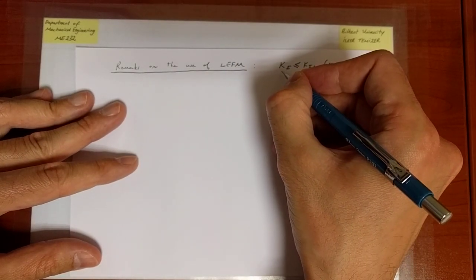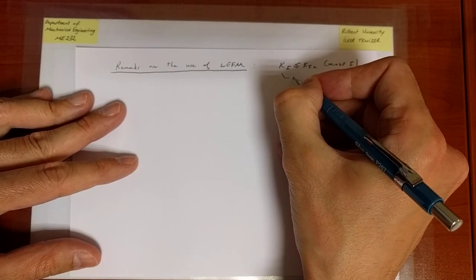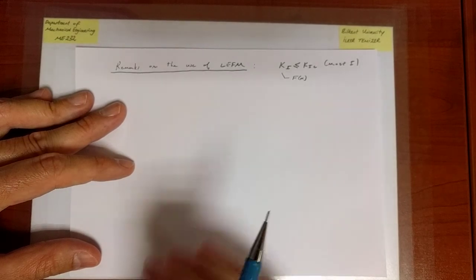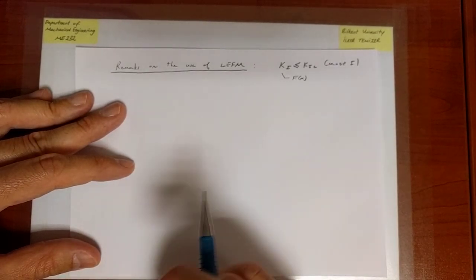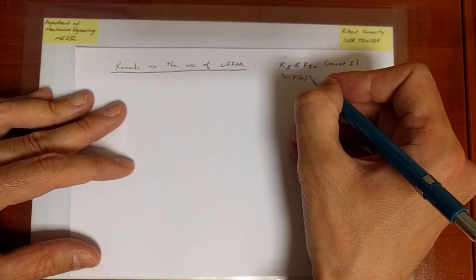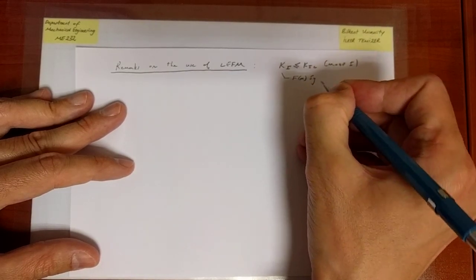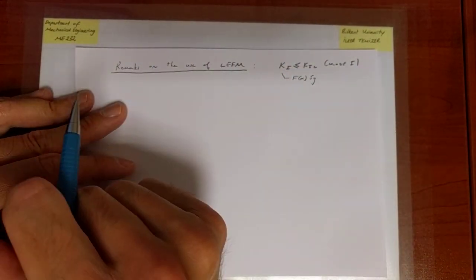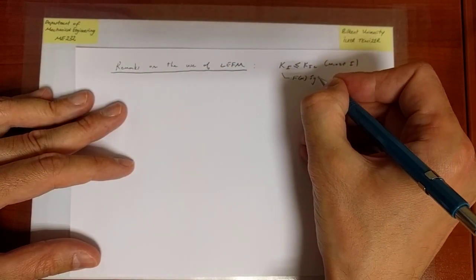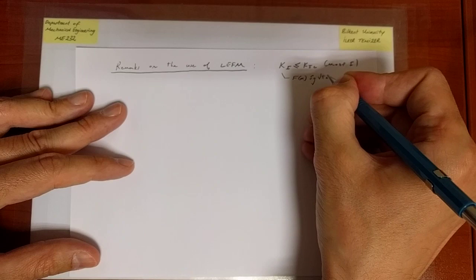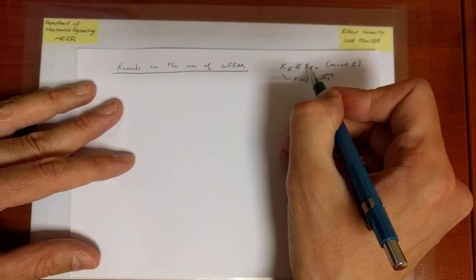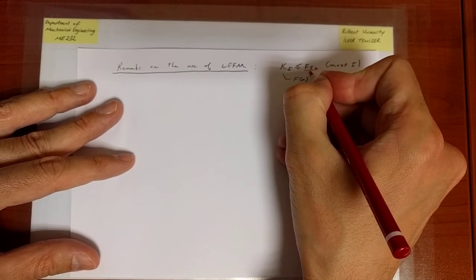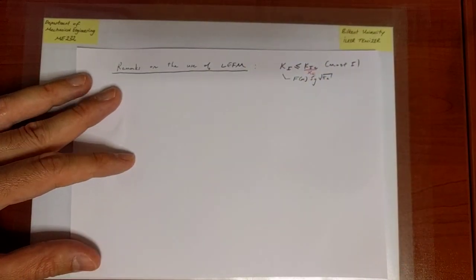And remember also that here, K is something that we know. It's going to be some form factor that depends on this value of alpha, which is a ratio of the crack size to a lateral dimension of the structure, multiplying the gross stress, which is always calculated at the cross section where the crack is present. We take the maximum value, but we do so by omitting the presence of the crack during the calculation, and then the rest is root pi a. That's what we would like to have. In general, of course, we would like to replace this by some safety factor, in order to predict some critical values, let's say, by some safety factor xk.